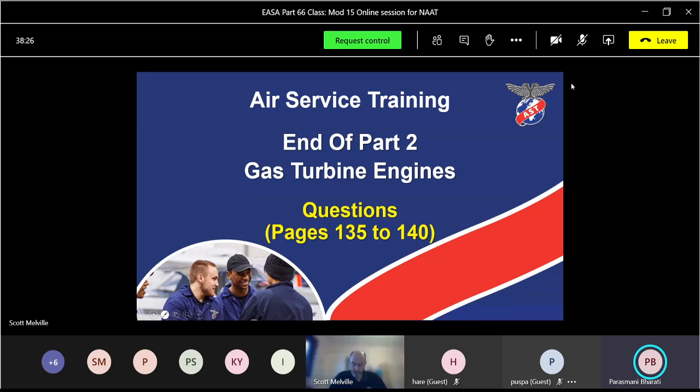Okay. How is fuel pressure generated in a fuel system? Fuel pump. Yes, the fuel pump provides the flow. It doesn't provide the pressure. It provides the flow, and then pressure is restriction to flow, which is through your pipes, your components, and all that sort of thing. Okay, good. My favourite one.